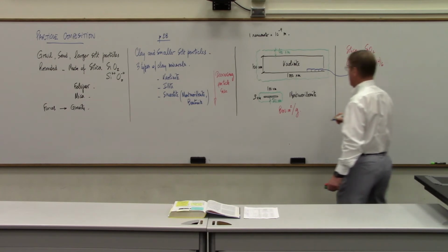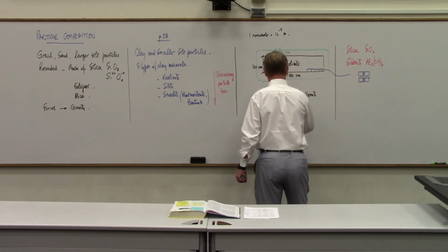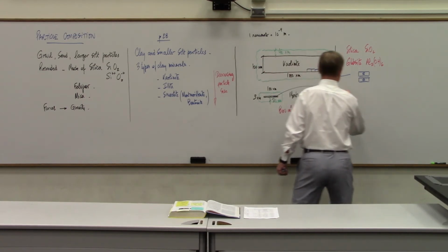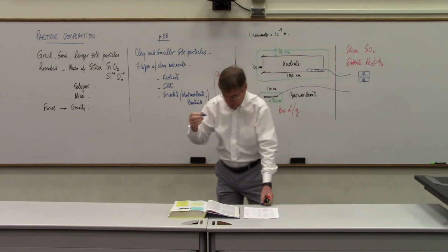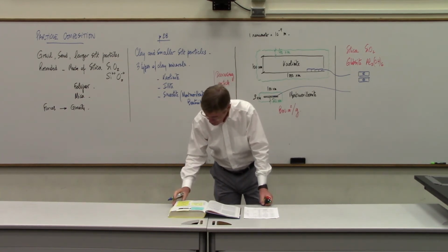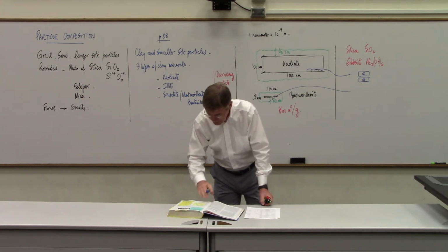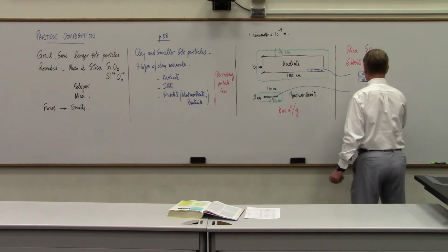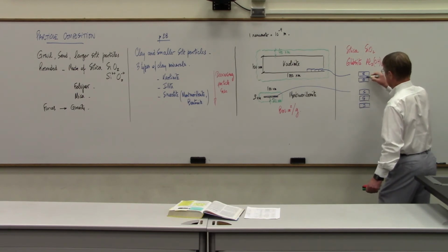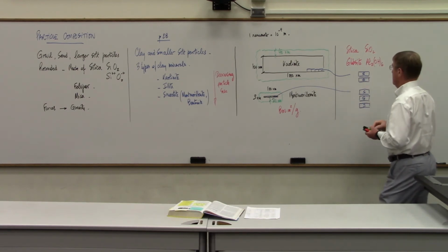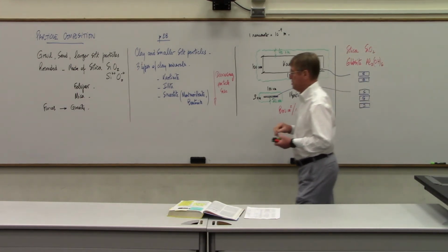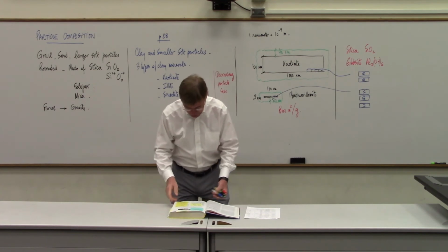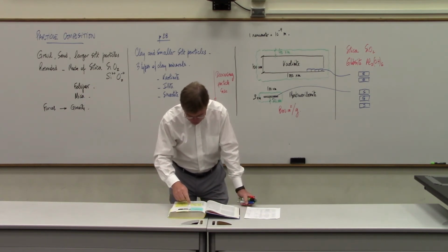Okay? And if I go into the Montmorillonite bricks, then these bricks right here are made of a layer of gibbsite sandwiched between two silica. So it looks like this: silica, gibbsite, silica. And that means that you can put water in here, water in there, but here you can only put it between those two. So this is detail, if you want, of what those bricks are going to be made of. All right, so I wanted to talk about this, then this.